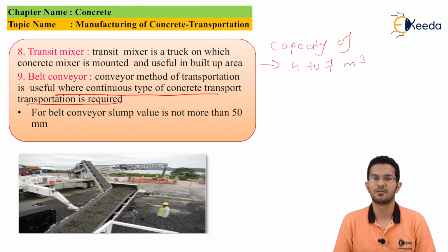If this method is used in adverse weather conditions such as hot and windy, the long reaches of the belt must be covered. If there is any breakdown of machines, a large amount of concrete on the belt needs removal by other means, and the belt is to be cleaned and washed. It has limited application due to chances of segregation on steep slopes, roller points, and changes in direction of the belt. It also involves overexposure of concrete to the environment.